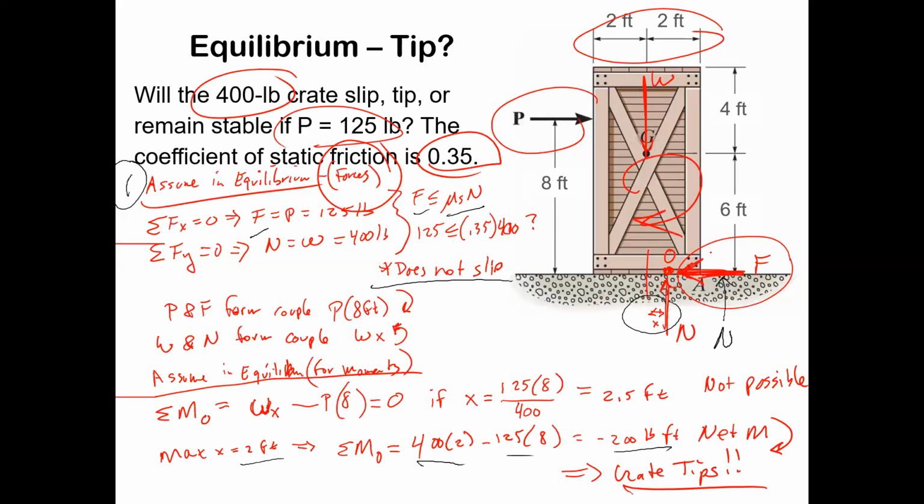That happens by the normal force where it's effectively applied, and this is a distributed load, but we have the effective load because it's sort of a trapezoid. It starts shifting to point A, shifting to the right. And that presents a countercouple to keep the thing from tipping over. Right.